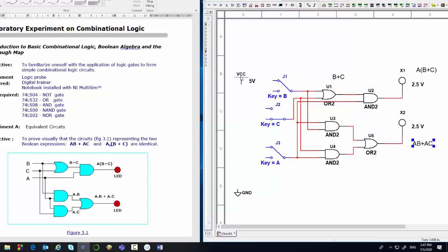Now, I have to connect the VCC to the switch as well. One end of the switch, the top part of the switch here, this is single pole double throw switch. So the upper contact point here, I will connect to VCC to make it consistent. Okay. Right, I move this end nearer here so I will not short the VCC to ground. And the lower part of all switches will be connected to the ground.